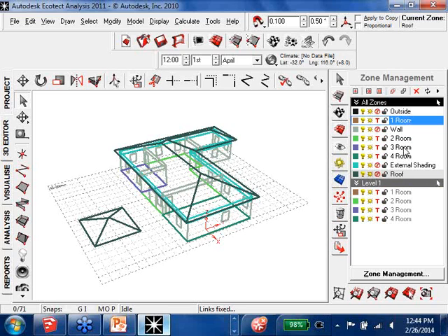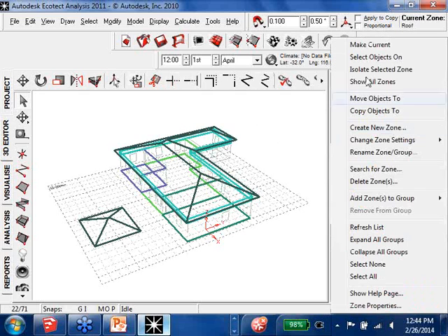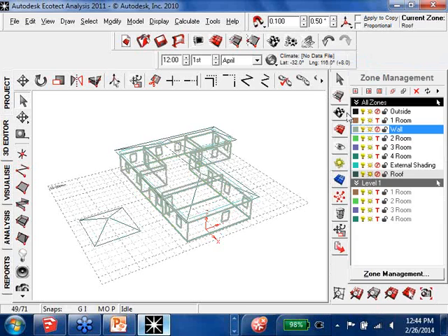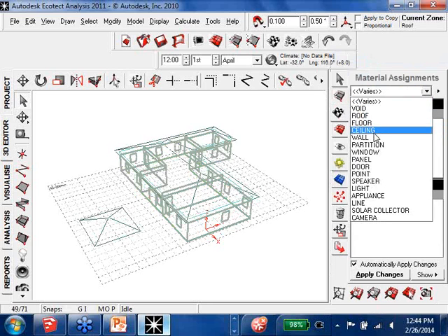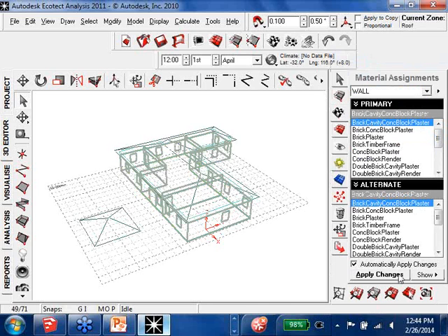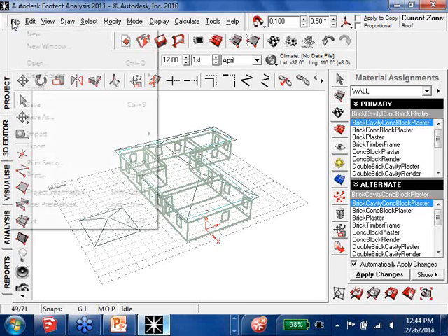So these are the objects that I did not add to different zones. So we have them in their individual different rooms, which we don't want. So I just wanted to show the difference in that. But once you add them to a different zone, then you can turn them on and off together. And it's much easier to select objects on and then apply a material to. So that's the ease of setting the layers up correctly as you go.